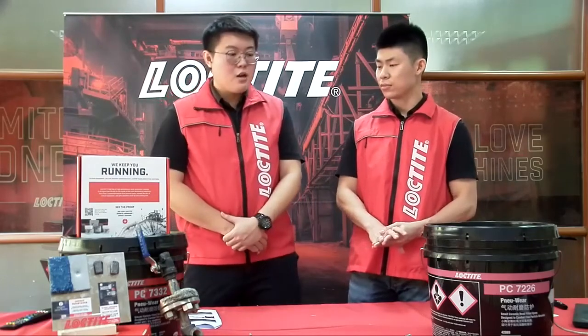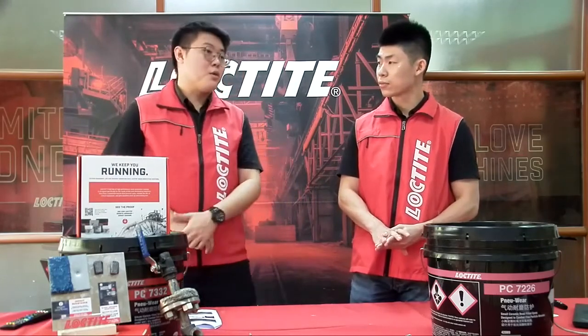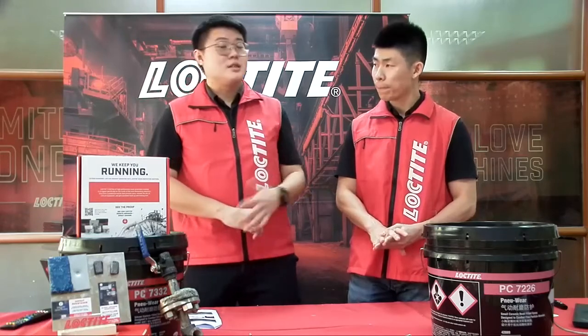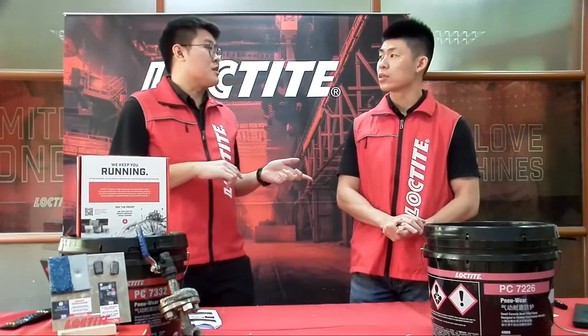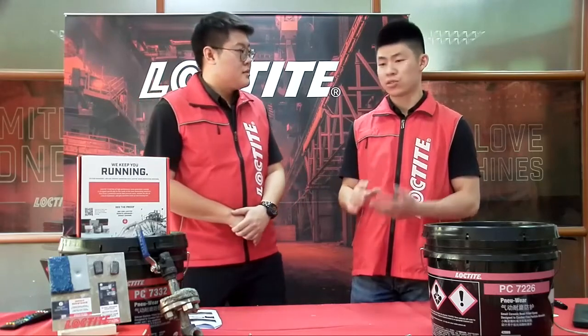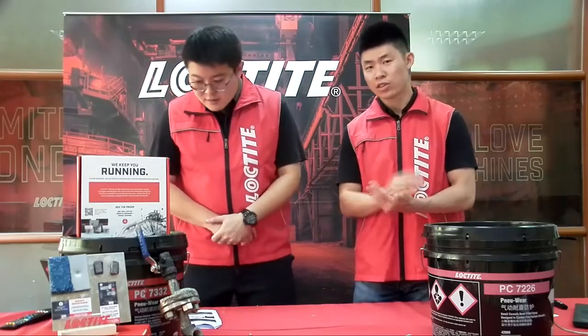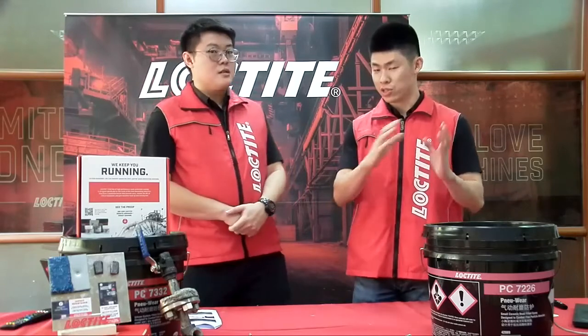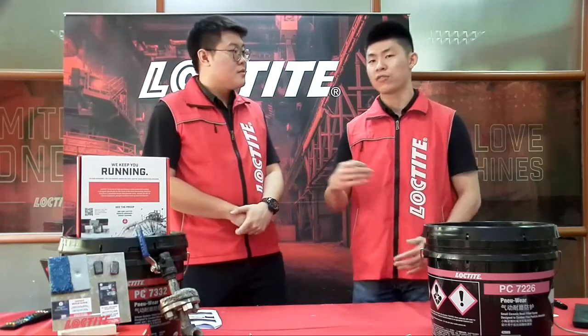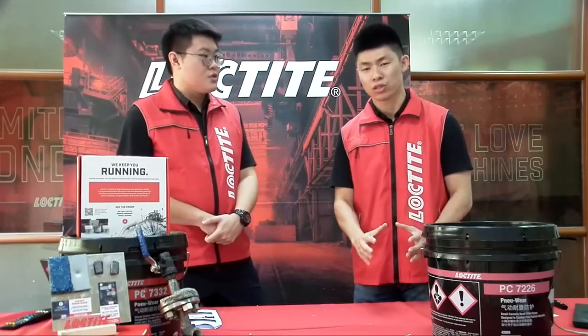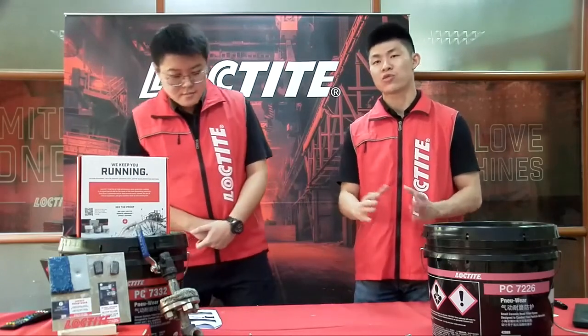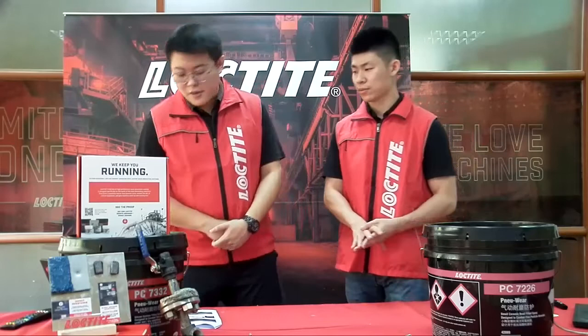And how about the pot life or working time? I think you mentioned earlier it's around 20 to 30 minutes. Yes, but this also depends on the volume. I'd like to take this opportunity to mention Loctite PC9593, if you still remember. Because of its faster curing time, that particular product has a much shorter working time, which is 10 to 15 minutes.